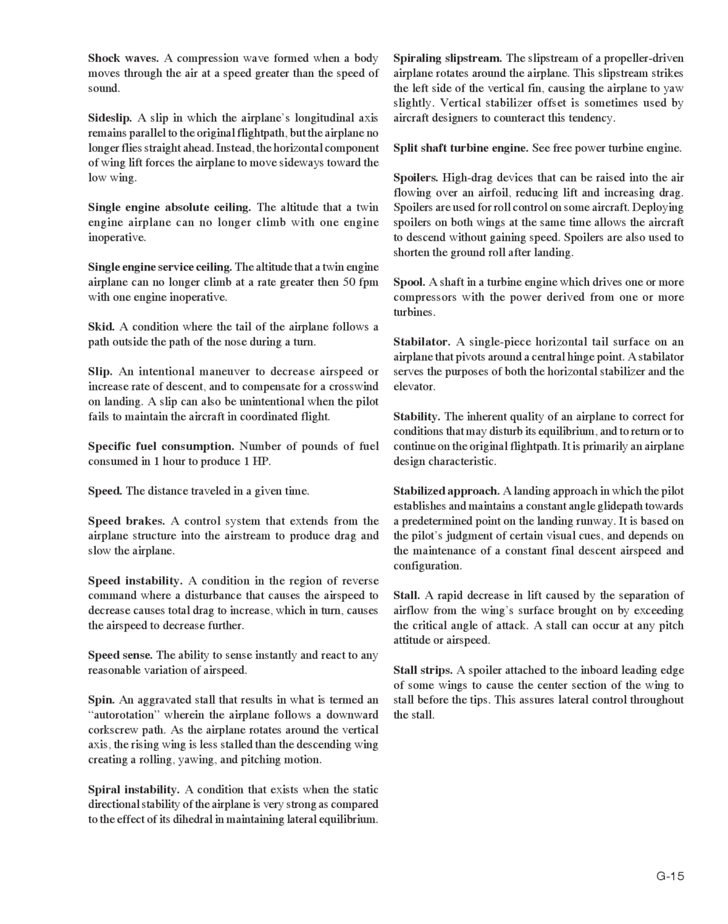Spin. An aggravated stall that results in what is termed an autorotation, wherein the airplane follows a downward corkscrew path. As the airplane rotates around the vertical axis, the rising wing is less stalled than the descending wing, creating a rolling, yawing, and pitching motion.